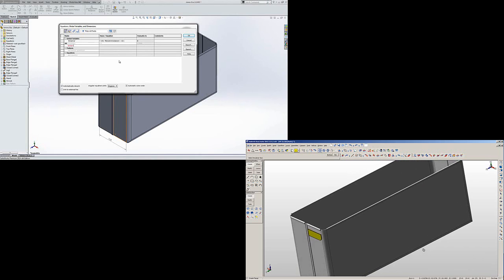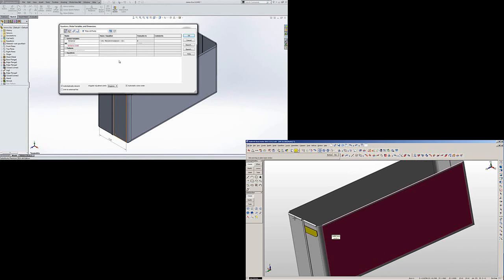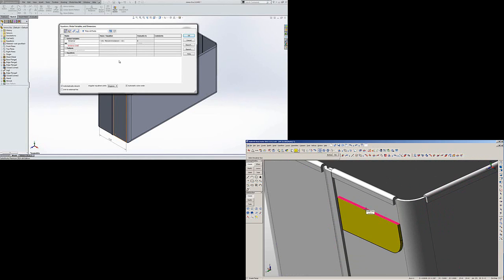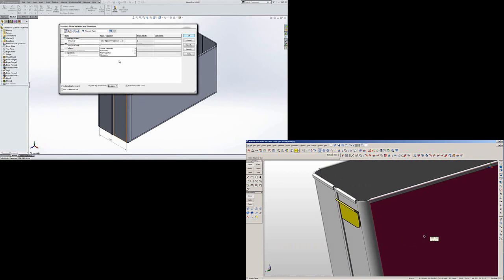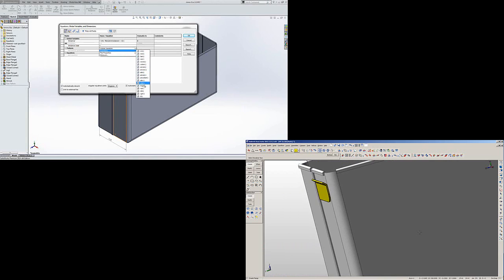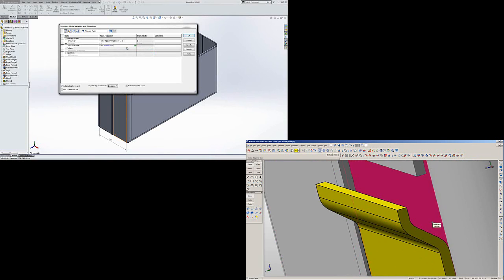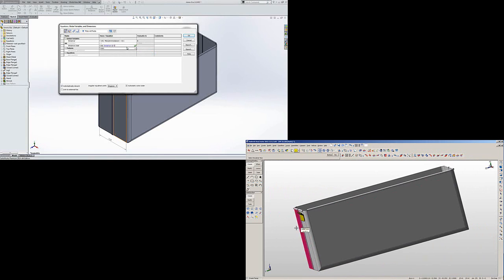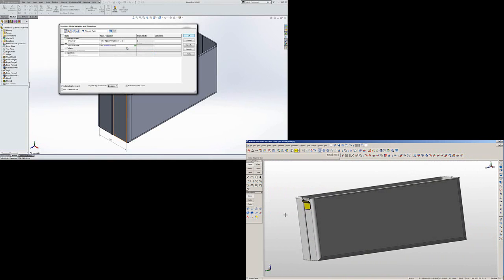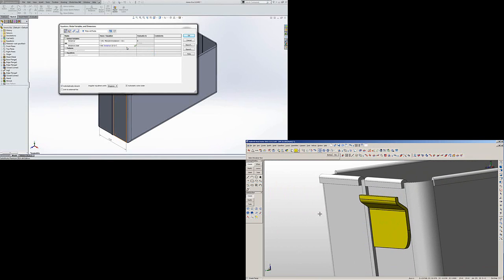Now it's because we are creating our hinge at the middle of our box, we need it to be an uneven number. So to do that, we can select our function again, int, and we're going to select our instance that we just created, so this one here, and we're going to divide that by 2, and outside that brackets we're going to times by 2 again, open a new brackets, and plus 1.